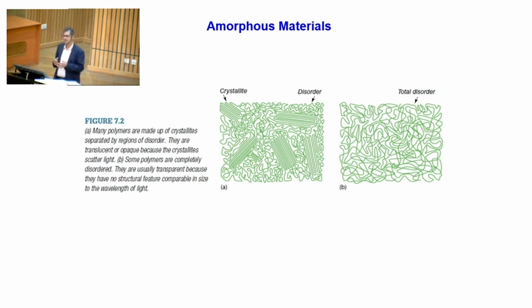So in such situations, the material has extremely high strength. You can't believe it. Strength can go even farther. If you decrease the grain size and make it amorphous, it can reach even 5-6 times that of the normal material. And people have seen it. But that increase of strength comes at the cost of ductility. Ductility and the fracture toughness reduce substantially if you are increasing the strength this way.